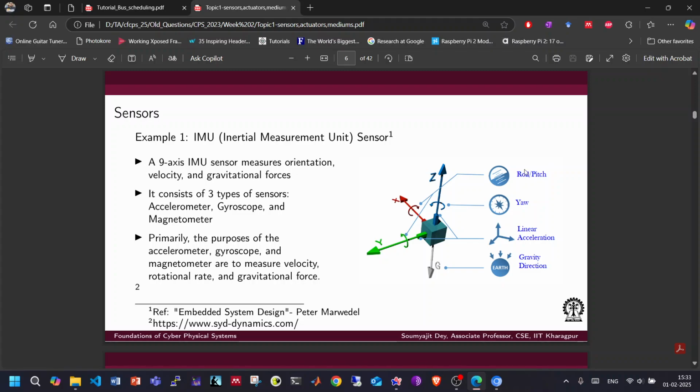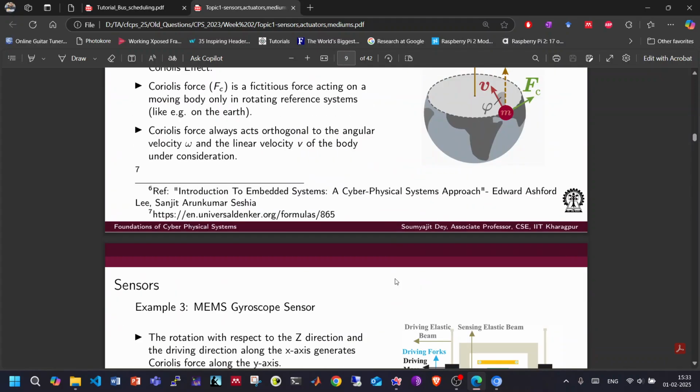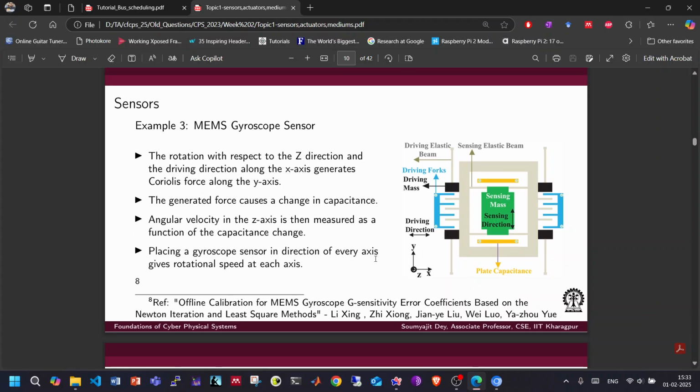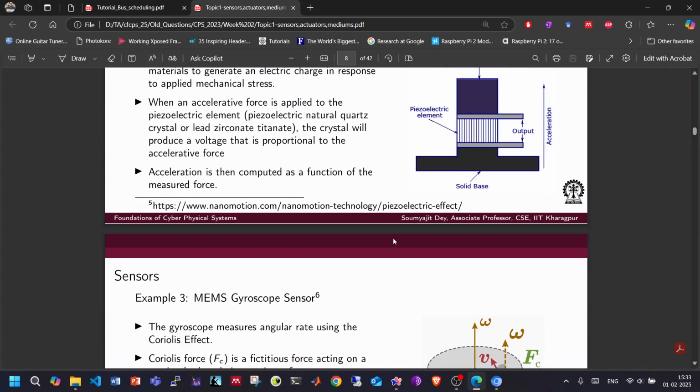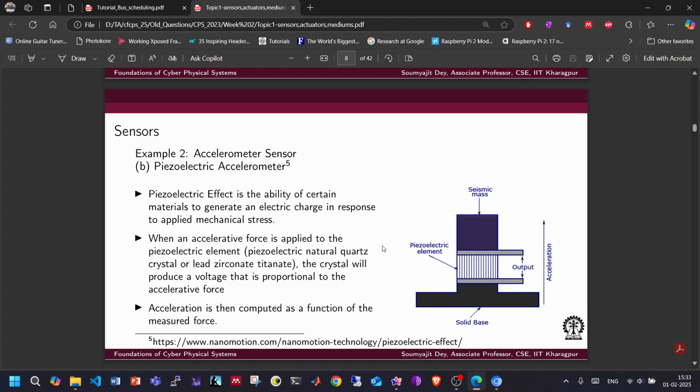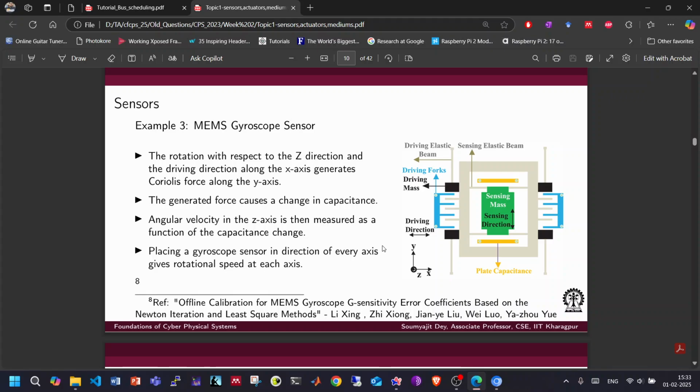Now if we come to the magnetometer. The gyroscope sensor again works in the same way as the accelerometer sensor. Here also you can use multiple different materials. If you are using a gyroscope sensor, you are trying to measure the inertia perpendicular to the x-axis, y-axis or z-axis by measuring, due to the Coriolis force, how much force is applied on the material.